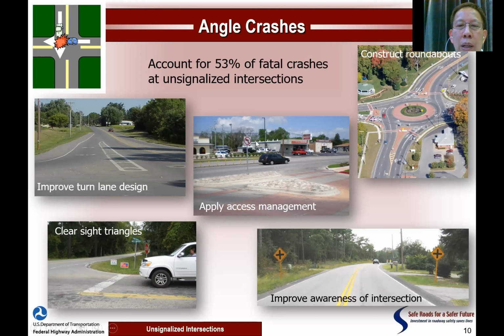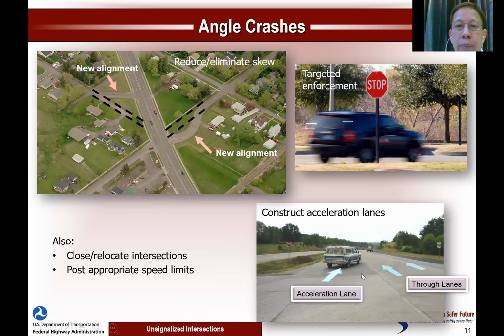Do not make a left turn. Construct something like a roundabout. Improve awareness, showing more signs and delineators on the road. Angle crashes.